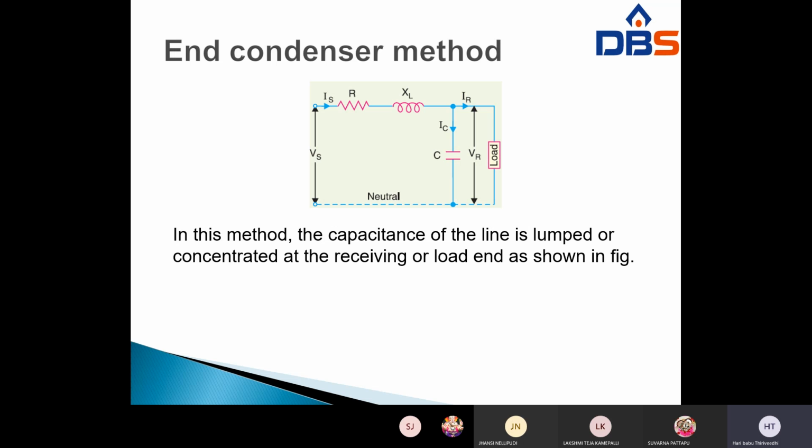So there is no phasor diagram here, I am explaining the phasor diagram. I already explained the phasor diagram for the short transmission line, right? Whatever it may be, first we take VR, the receiving end voltage, as the reference, and the current is lagging, right? IR is lagging.